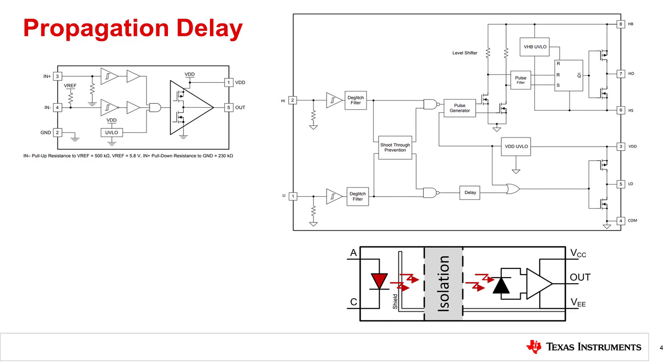Opto-isolators convert the gate drive signals to an optical signal with an LED, and the signal is detected by a photosensitive circuit such as a phototransistor or photodiode. LEDs, driven properly and with minimal additional parasitics, can switch on and off in tens of nanoseconds or less. With proper optimization of internal parasitics, transimpedance amplifier characteristics, LED drive strength, and many other design values, opto-isolators can achieve propagation delay similar to capacitive or transformer isolators, for a cost.